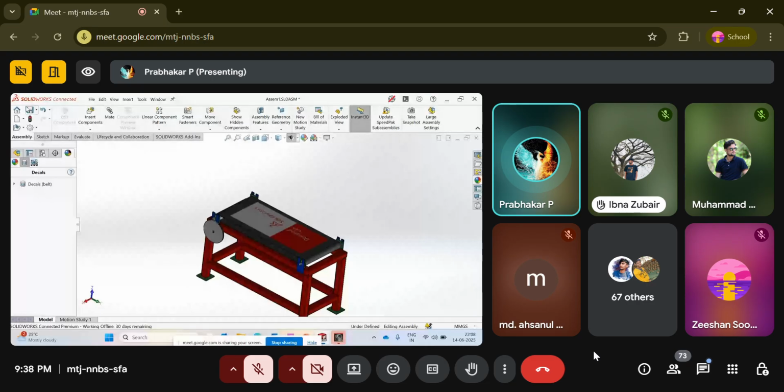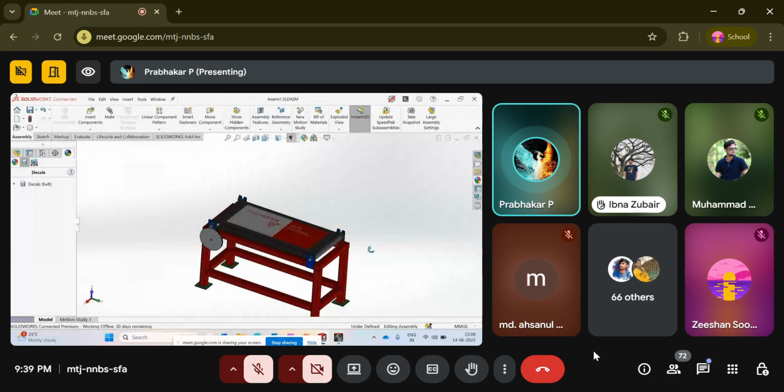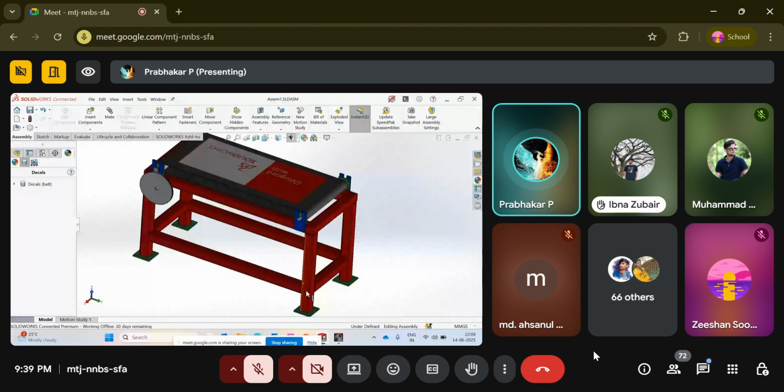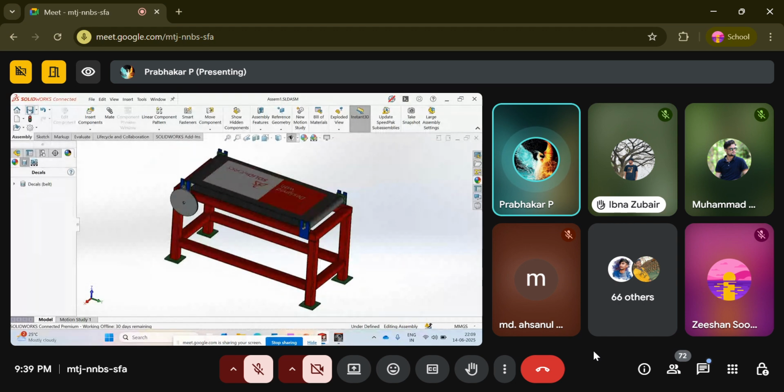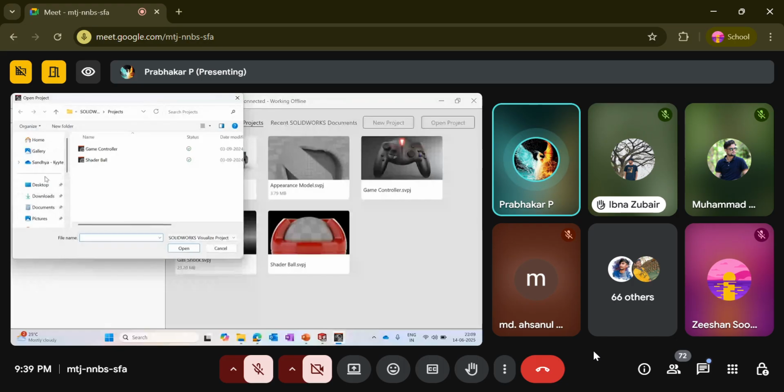Now I will take you to the rendering environment. First, I can give the orientation here, which orientation I want to do rendering in, everything. I can set it here only. Now I set the orientation here only. In this orientation I want to do rendering. So all these things, whatever I have done over there in SolidWorks, can be done here also. Since everyone will be aware of SolidWorks, I just did that there. Here I select SolidWorks documents. Assembly1 is the file name.